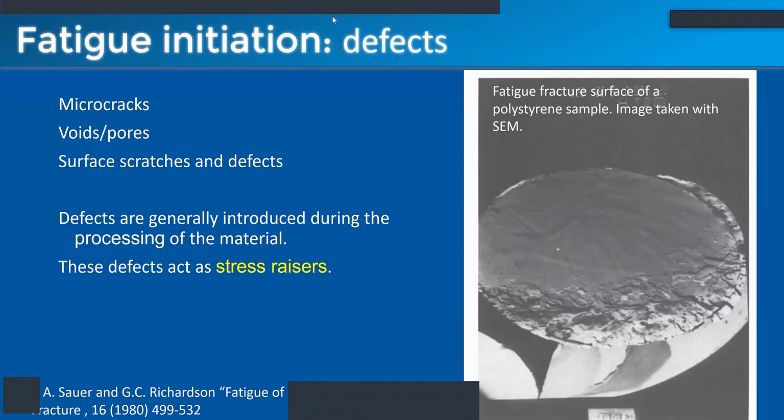And there are a couple of vocabulary terms associated with fatigue testing, which is what these few slides are intended to describe. So the first is fatigue life. Fatigue life would be how many cycles it takes until the material fails, given a certain applied stress. As we increase the applied stress, the fatigue life, or the number of cycles to failure, is going to get shorter. You can see that as you move from right to left on the plot. And that makes intuitive sense.